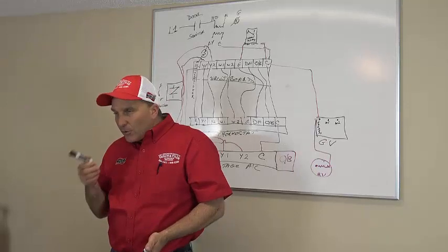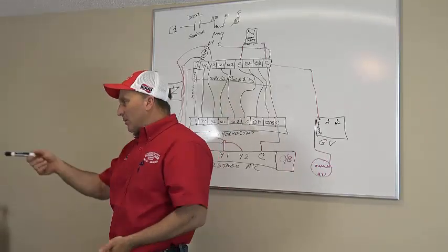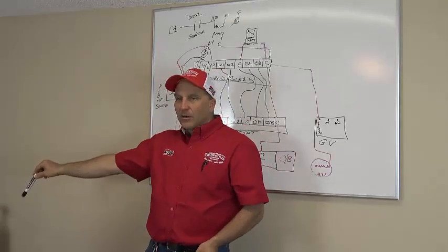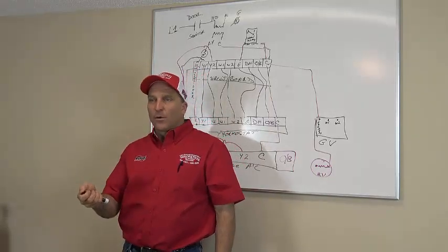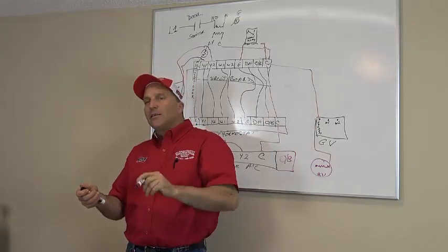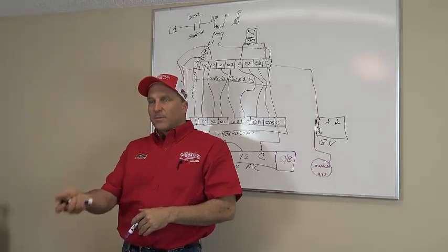But if you look at your relays and you see a blue wire that's jumped from that one to that one to that one, you can go over here and take your common and go, boom, I'm over here on this common, right? Or I can take it right from my transformer, boom, 24 volts, right? And then I can follow my R all the way through my relays and limit switches and float switches and the whole nine yards, right? So one of them stays still.